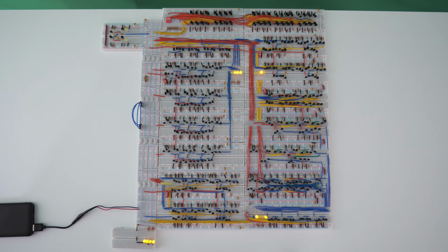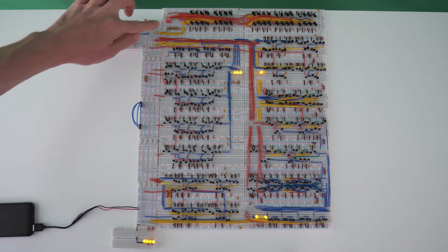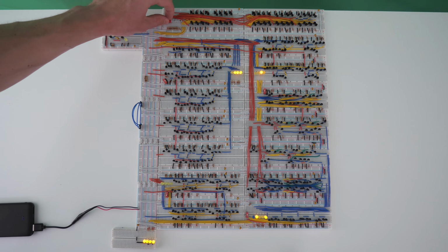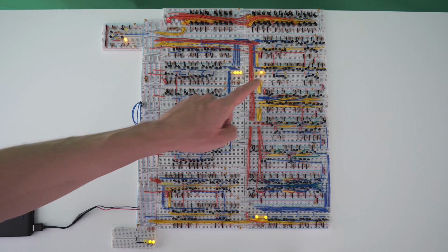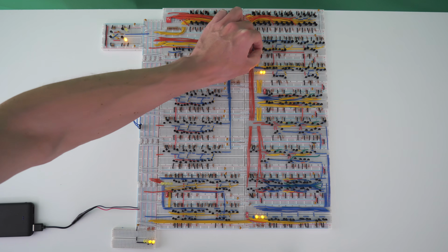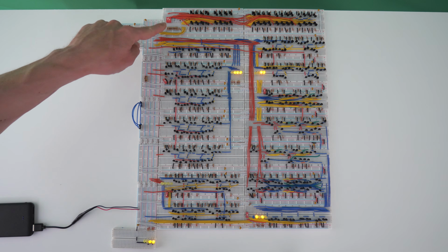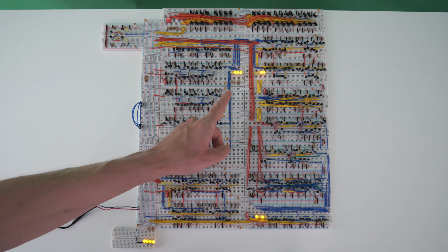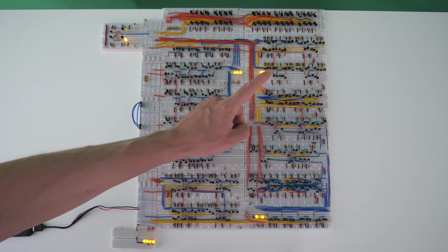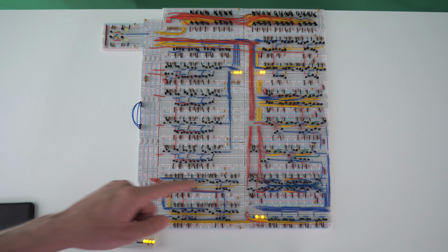Next, we're going to do a subtract. So this one is going to be different. This time we're going to use the third value in our memory. So now we have a value of 3 on our data bus. And we're going to load that into the B register. And then we're going to turn this off so it's no longer connected. So now you can see that we have 7 plus 3 equals 10.